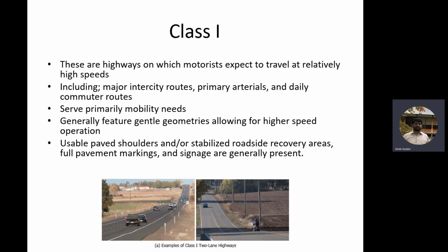So again, coming back to the concept of how do we maintain high speed. First of all, the geometry of the road should be gentle: more width, radius, gradient and so on. Then we need other features as well to maintain high speed. For example, shoulders are very important for maintaining high speeds. Shoulders provide clear space, and a space to park your car if something is wrong. Without shoulders, it becomes very dangerous and people will eventually slow down.